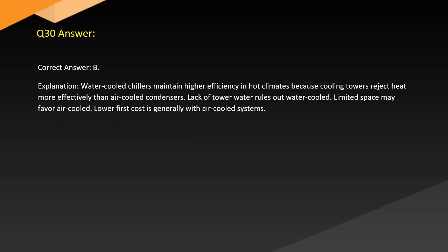Answer. Correct answer: B. Explanation. Water-cooled chillers maintain higher efficiency in hot climates because cooling towers reject heat more effectively than air-cooled condensers. Lack of tower water rules out water-cooled. Limited space may favor air-cooled. Low first cost is generally associated with air-cooled systems.